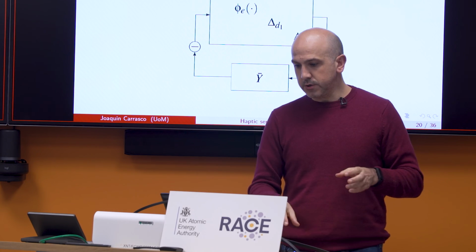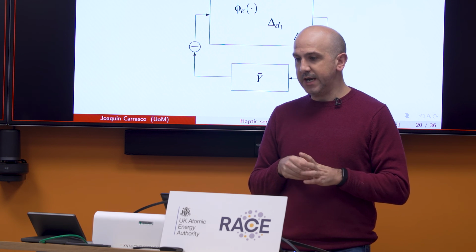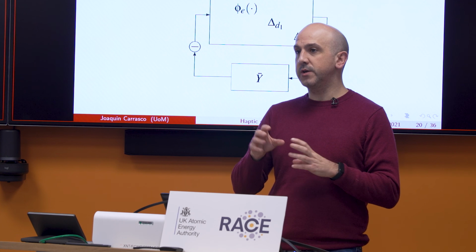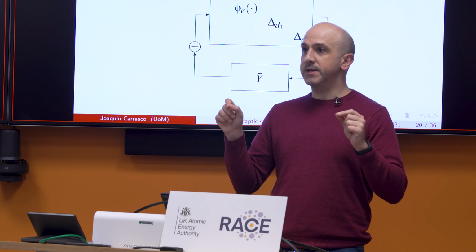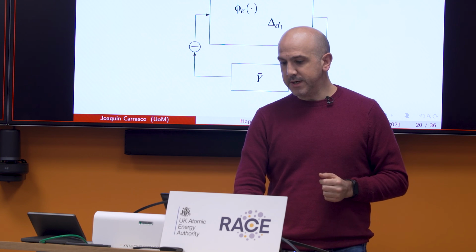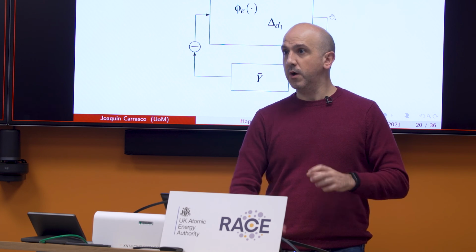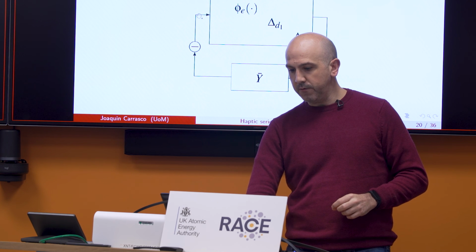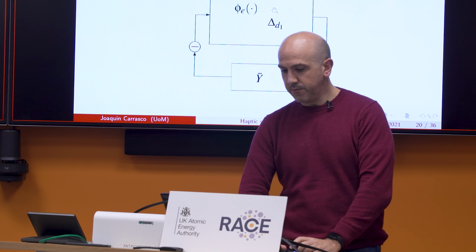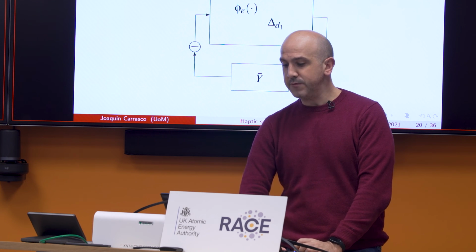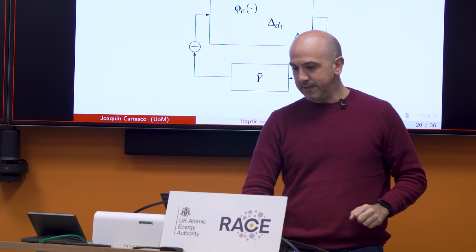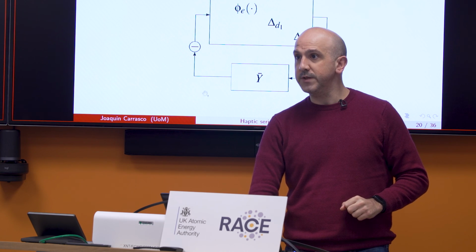So in the Lur'e structure, basically you use what is called the IQC theorem, which is kind of the same concept as previously. What we are trying to make sure is that the properties between the input and the output of this block, if you think of this guy and that guy as input and output, have to be in a different set than the properties of the input and the output of this other block.